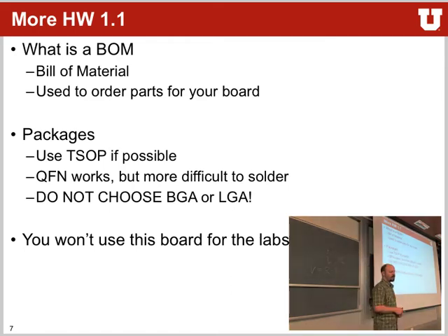Again, back to the packages. So use the TSOP packages if possible. Yes? Can we use DIP? You can use DIP if you want to, yes. Now, somebody else would inform you that DIPs are not supposed to be soldered into PCBs, but let's just go with it for now. Usually for DIPs, so DIPs are the ones that have very big leads on the outside, very simple and easy to solder. So usually you have a socket that actually solders onto your PCB, and the DIPs go into it.